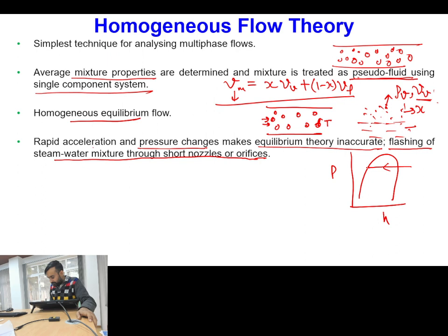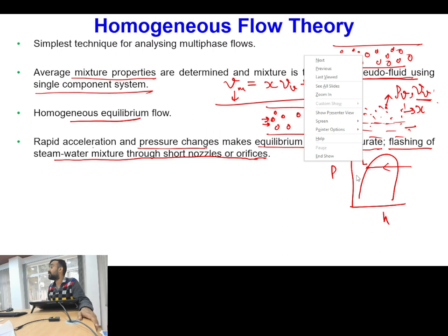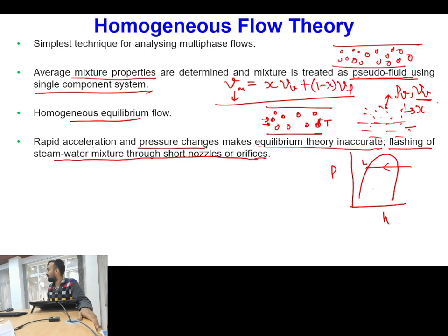This is your condenser. At the exit of the condenser, I have subcooled liquid, sorry, saturated liquid. When this saturated liquid is passed through a throttling device, a capillary tube, it enters into a lower pressure, which is the evaporator pressure. Here PC is greater than PE. The process in the throttle is represented by a dashed line.